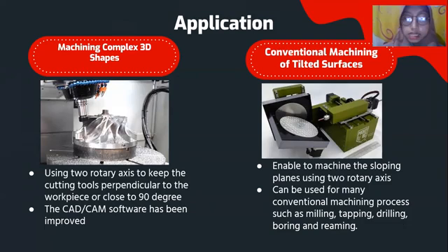The CAD and CAM software used in this application has been improved very well. The design engineer's 3D drawing can be directly imported into the CAD system, and once it is imported, the programmer's task is relatively easy. Choices in machining method are numerous, and the programmer can command the CAM system to progress from roughing the workpiece to finishing it with successively smaller cutting tools.